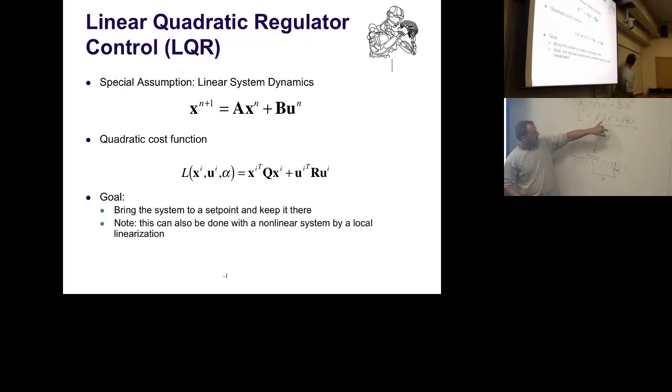Again, now these values in the Q and R matrices become critically important. If you put very big values into R, that means you want to have minimal motor commands. You will go very, very slowly in order to get there. If you put very big values into Q and keep R small, you will be very aggressively racing for the goal and trying to stabilize there. And you will see there will be solutions which oscillate a lot initially and then come to rest, or some which go beautifully smoothly there.